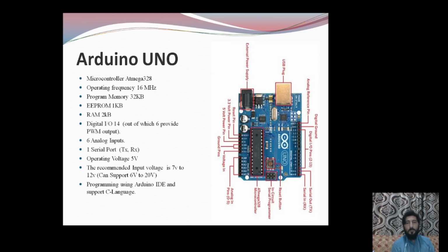Once again, for input voltage the recommendation is 7 to 12 volt. If you need to interface other components which need an operating voltage of 5 volt or 3.3 volt, then this board will also output 5 volt and 3.3 volt. It has an onboard regulator that converts to 5 volt and 3.3 volt. A reset button is also here if you want to reset the program while running.